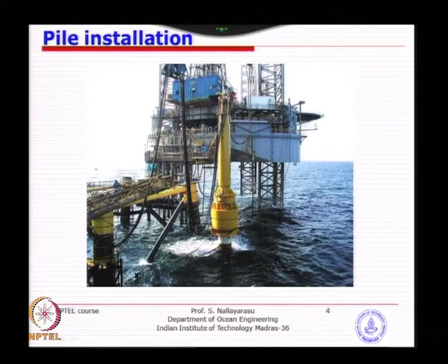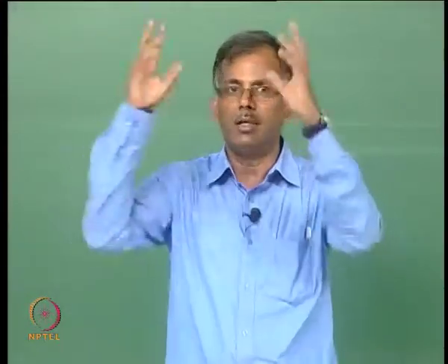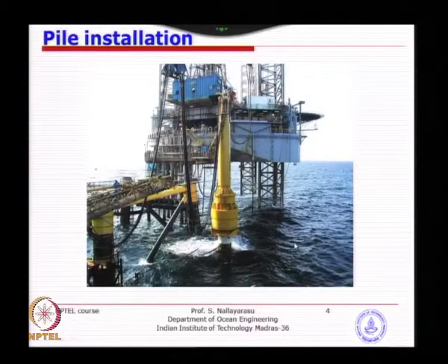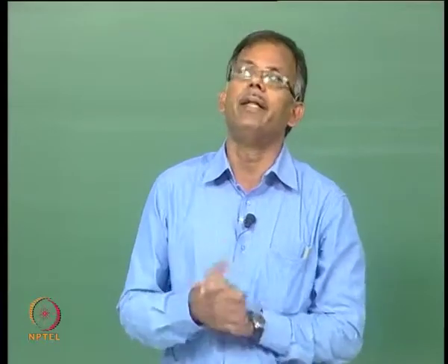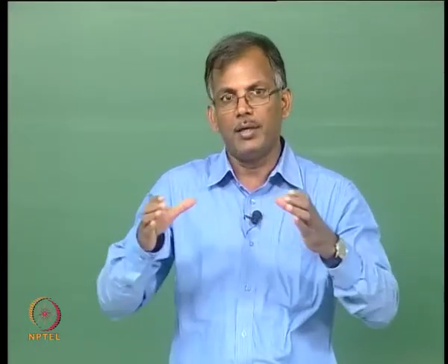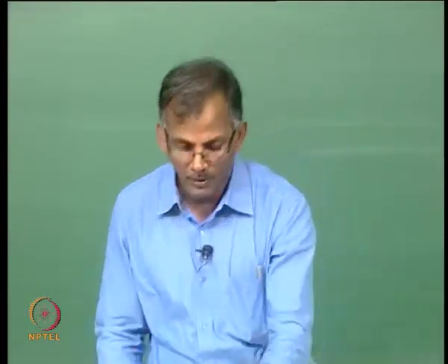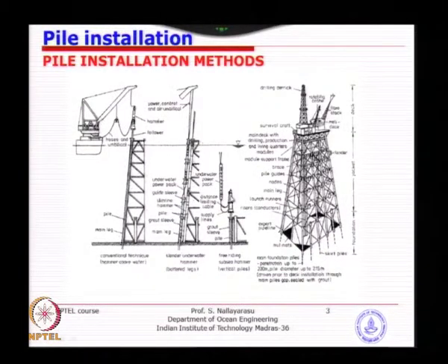The hammer will be supported on top of the pile itself. So imagine when we are driving, if it is 100 meters sticking out at the initial stage, you put a hammer of 100 tons and you have sea state wave conditions and the current, the pile is going to oscillate like a cantilever. So the stresses due to wave, current and the deflected shape with the hammer on top of it will cause a huge bending, and that will mostly govern the design. So the diameter has to be bigger and the thickness has to be larger, and those are the challenges of installing such a type of skirt pile.